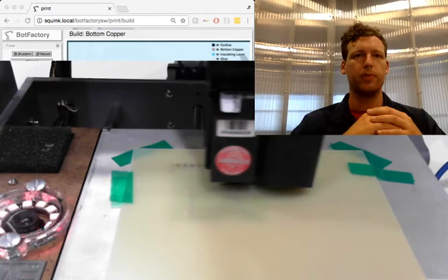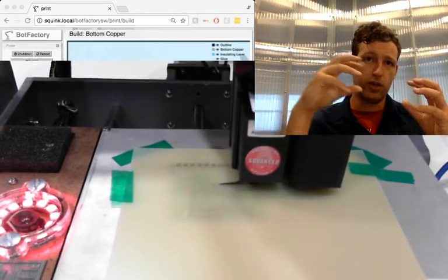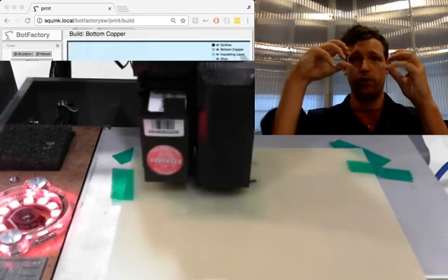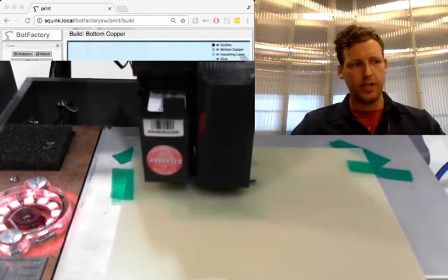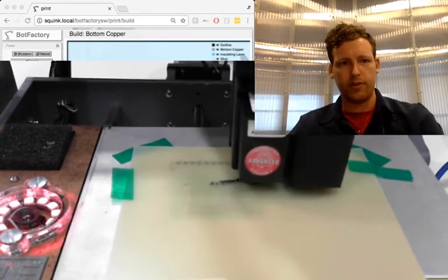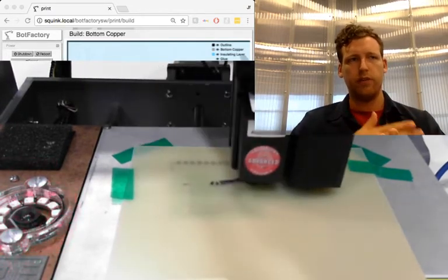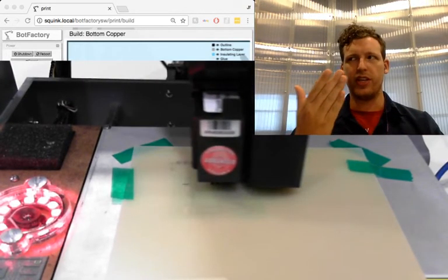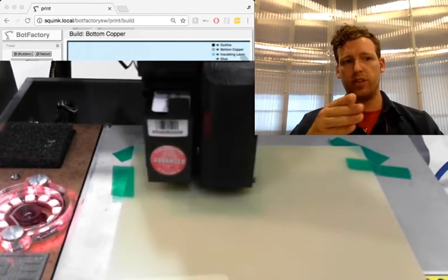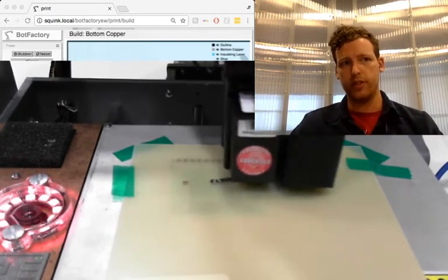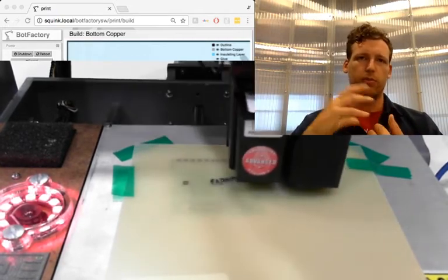But essentially, the machine jets them using a thermal jet technology. We have a small heater that creates a small bubble in this chamber, forcing a controlled amount of ink out onto the bed. The heat, right now we're running at 80 degrees Celsius. So 80 Celsius is what we need to do minimum sintering. If we go any higher, we find that the heat tends to damage the nozzles and shortens the life of the cartridge. So we do a two-step process. When we're printing, we print at 80 Celsius, and then we go to 110 Celsius for 20 minutes to complete the sintering.